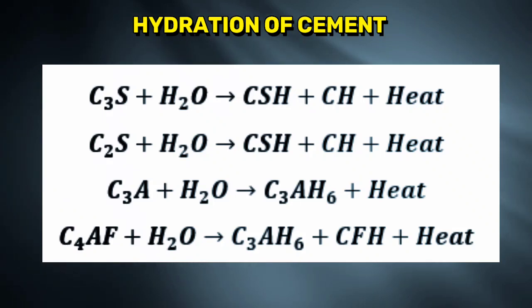So the C2S, which is the dicalcium silicate, hydrates and hardens slowly and is largely responsible for strength increase beyond 1 week. Okay, then the C4AF, that's the tetracalcium aluminoferrite, hydrates rapidly but contributes very little to the strength.